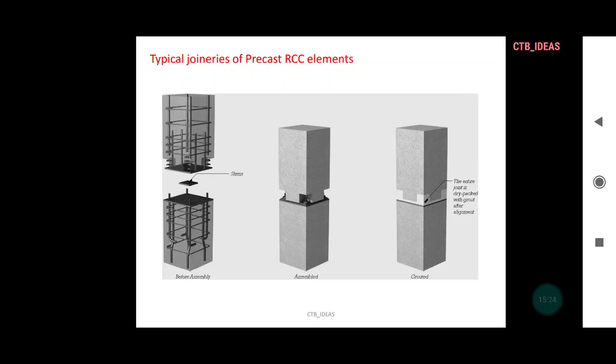The precast concrete columns are connected together through bolting. The top of the lower floor column contains threaded bolts projecting out, while the bottom of the upper floor column has an embedded base containing holes to engage the bolts. The blockouts in the column above, the holes, are filled with concrete after the connection has been made.